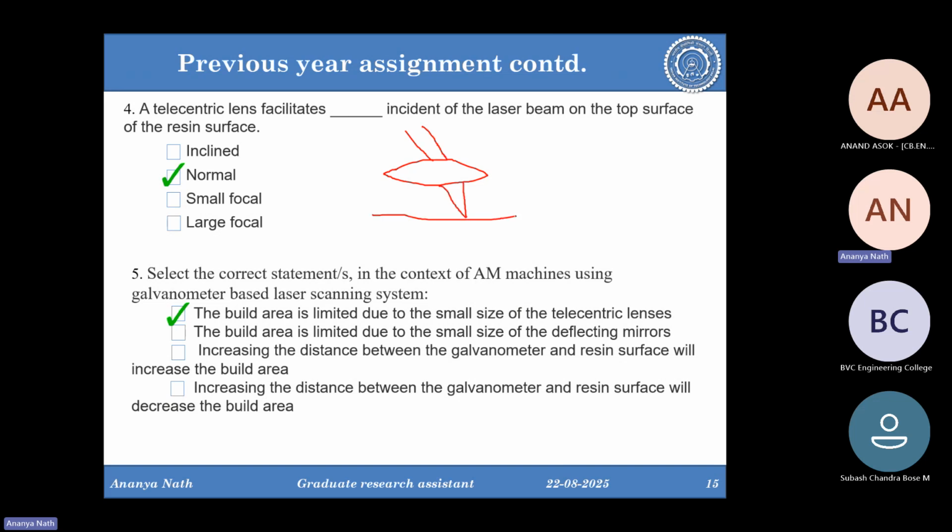Now my build plate is flat, so it will focus my laser onto the build plate no matter where it is pointing. But due to this way of focusing the laser, even if it's focused, if you zoom in, the laser spot diameter has been distorted into an elliptical spot instead of a circular one. We are supposed to get a circular spot, but we are getting an elliptical spot because it's expanding the laser. That's why it's elliptical. Now, if it's elliptical, our energy density will change.